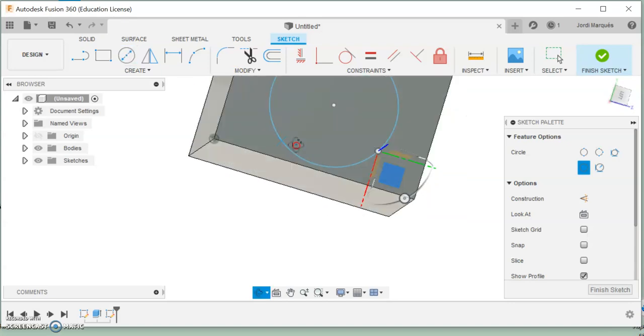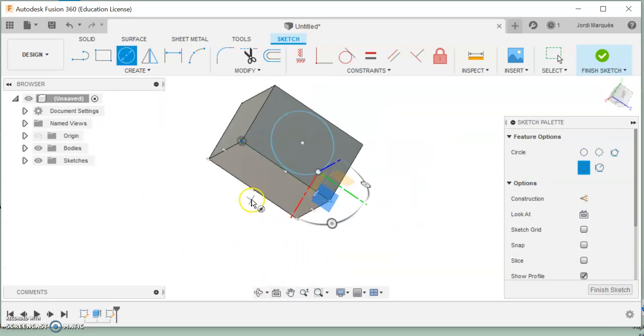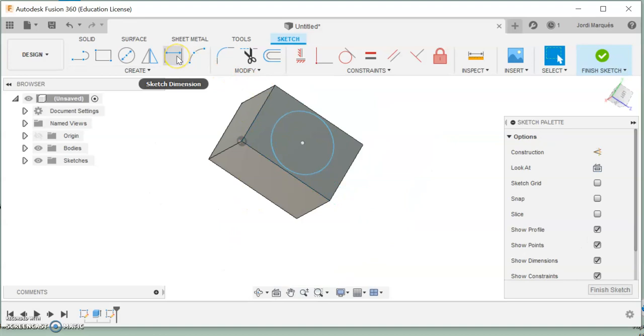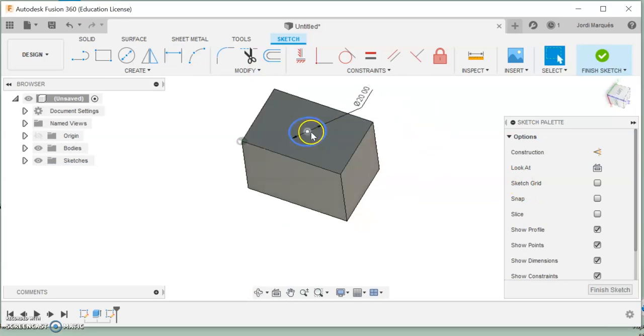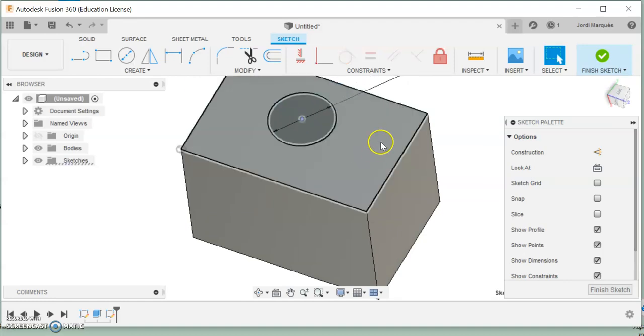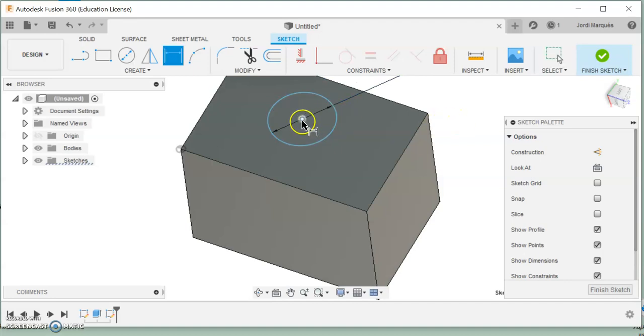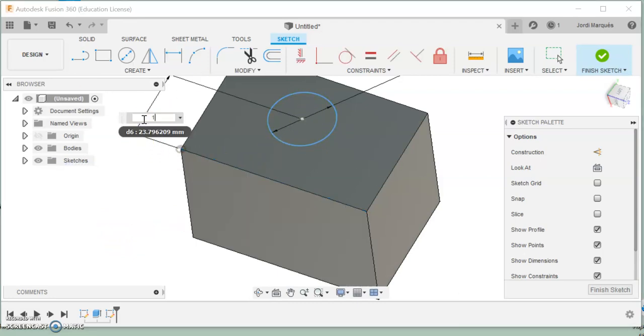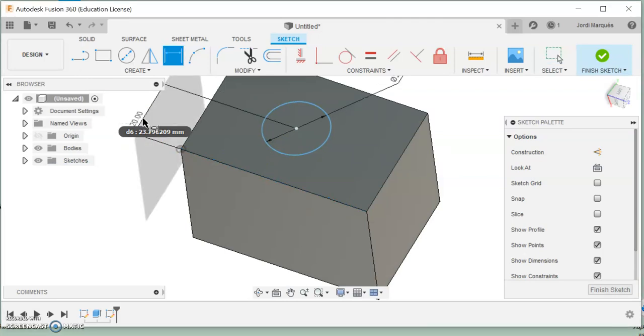Here we have our circle defined as we said before. We go to sketch dimension, or we click D, 20, escape. We can see it's in blue, so it is not defined because I can move it. So you need to have it locked. D from dimension, we can go here, yep. D, and point the other 20, 20.